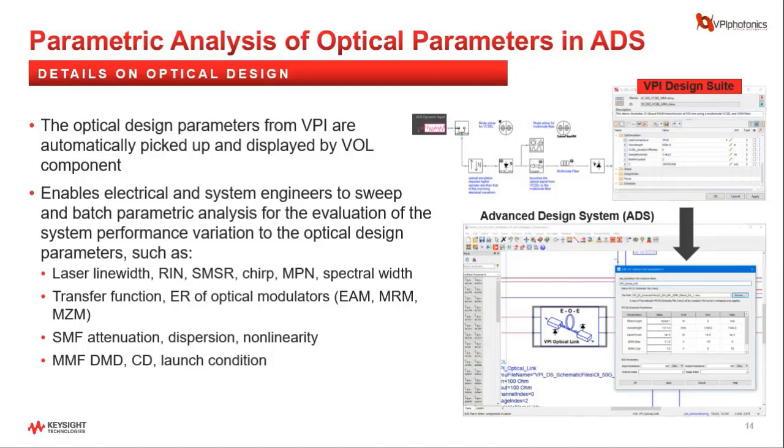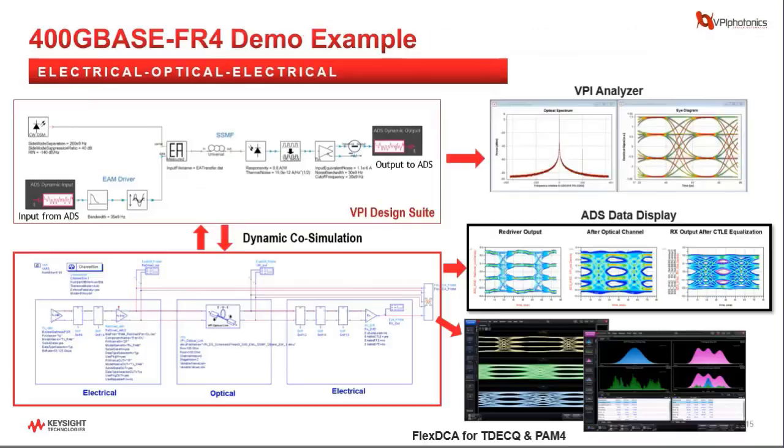This really enables electrical and system engineers to sweep or batch simulate to do parametric analysis for the evaluation of system performance variation to the optical design parameters, such as laser linewidth, RIN, SMSR, chirp, MPN, single mode fiber's attenuation, dispersion, and so on and so on.